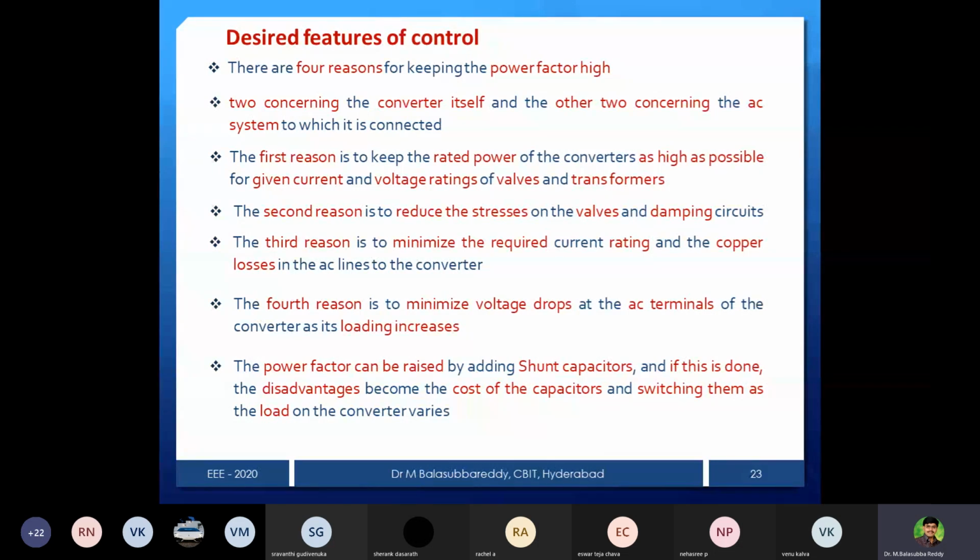So what is the compensation? The reactive power will be absorbed by the induction motor. So you keep a capacitor or condenser there itself, so that whatever reactive power is going to be absorbed, you can increase that reactive power supply through the capacitor. The capacitor will generate the reactive power, so that both reactive powers will get cancelled out. That is the compensation for constant voltage.